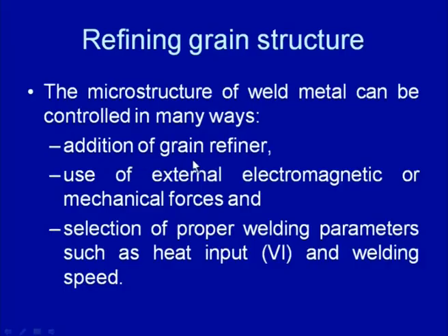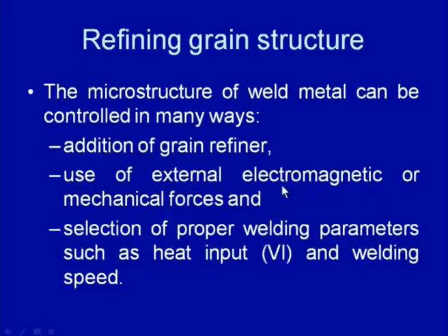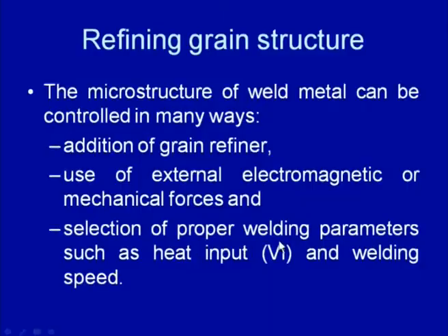The refinement of the microstructure of the weldment can be achieved using various approaches like inoculation, where the grain refiner is added from outside, which can act as a nucleant to refine the grain structure. Another is the use of external force, like electromagnetic forces or mechanical force in the form of mechanical vibrations. These methods are basically used to create a disturbance in the weld pool, so that dendrite fragmentation and grain detachment can be obtained in order to produce a large number of nuclei in the weld pool, so as to refine the grain structure.